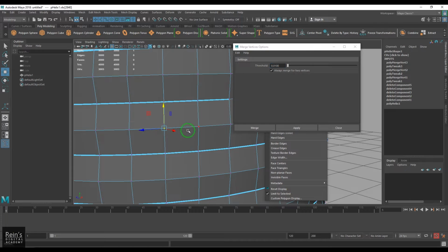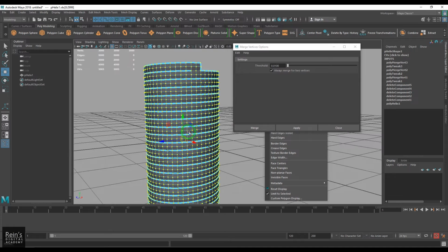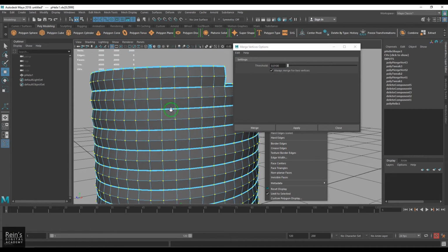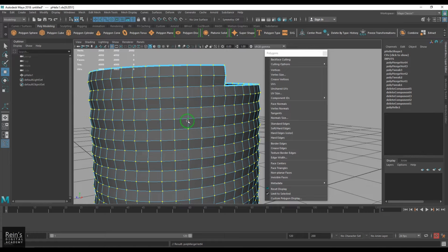So this vertex and this vertex are too far from each other, they don't get merged, while we have these two vertex points, 1 and 2, they are close to each other and they get merged here. So select all of them like that, and with the default setting, you should see things merge. The thick line will disappear if the merge happens correctly. So let's do it, and then you should be able to see that's done.